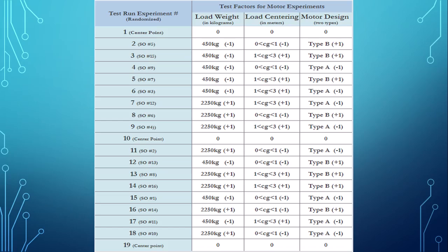The reason for randomizing the experiment is to help account for outside variables of influence. If 2 like combinations are run at different times and temperatures, it will eliminate both of these variables. Adding center point runs is a final important aspect of full factorial experiment design because it proves whether the relationship between factor and output is linear or not. If the relationship is not linear, then the result will be misleading and a different type of experiment design should be used.